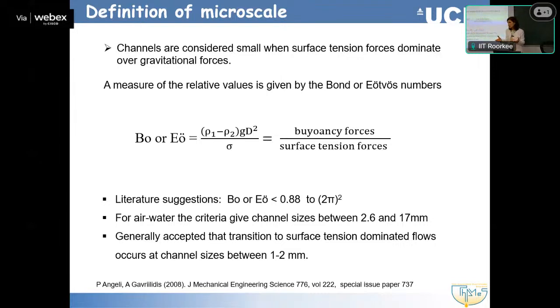With channels that are sub-millimeter, we really need to be clear about what we want to do with these small channels. If production is what we are interested in, then we should be pushing the size, because otherwise we'll have problems with high pressure drop and low throughput.